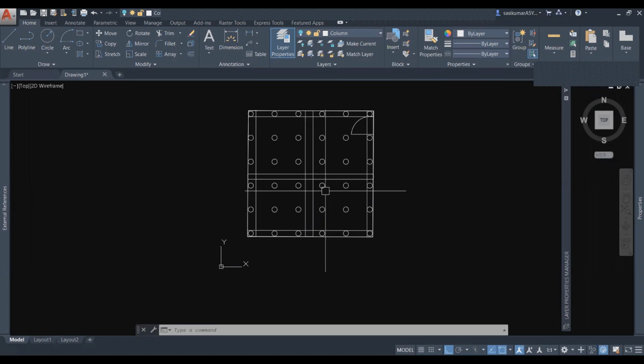Because sometimes if you want to create lighting elements on your plan, there are a lot of things in the drawing, it's very messy and not easy to read everything. So in that case, you just turn off everything, turn on only the column, wall, slab, the room name, then easily you can place the lightings, easily you can place the ACMV elements.